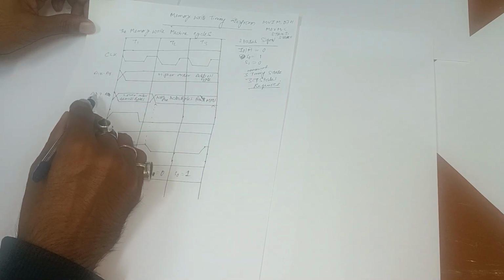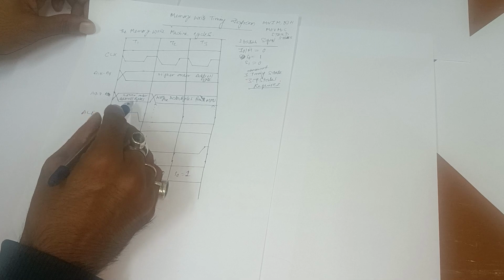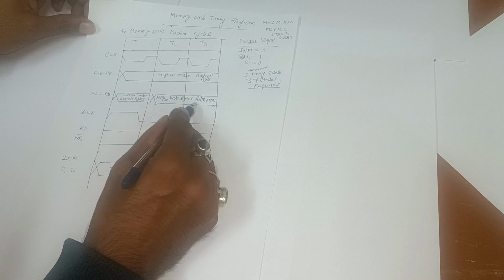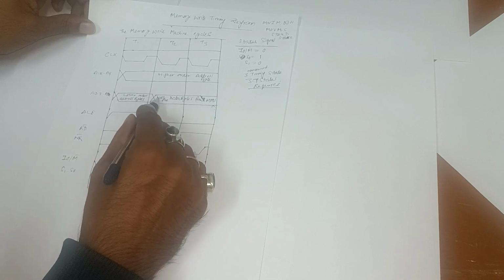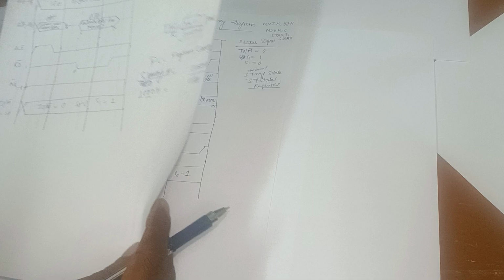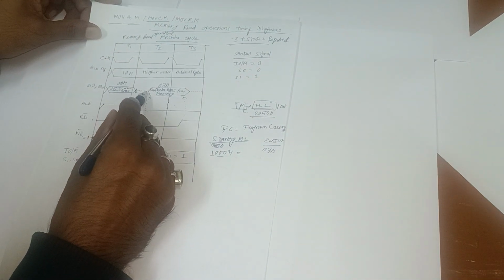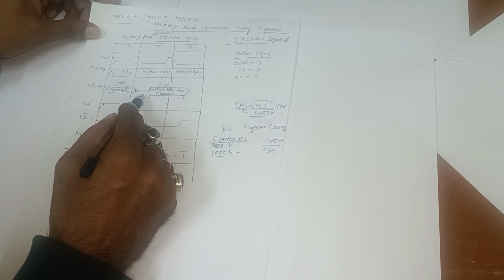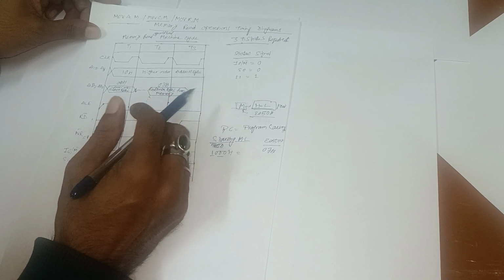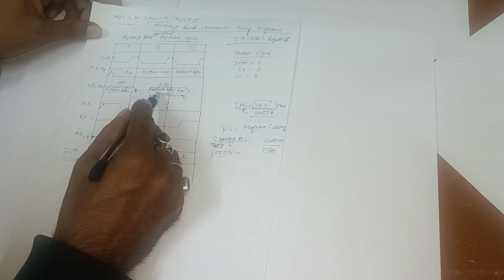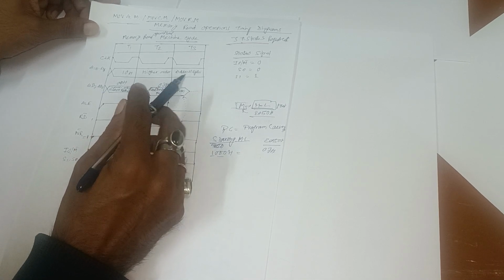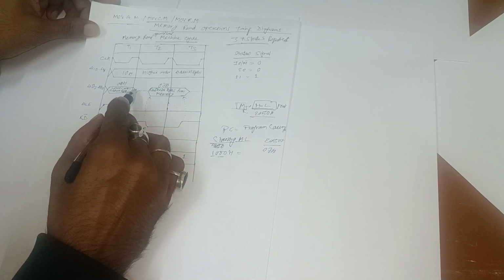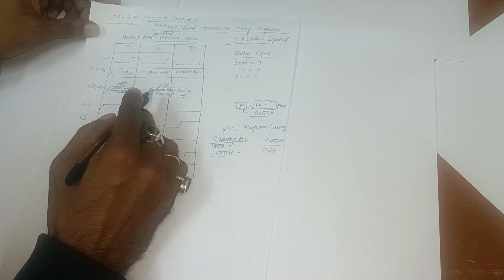Again AD0 to AD7 is the multiplexed bus. For this multiplexed bus, obviously you first have to take the lower order address byte, then T2 to T3. Why is there no gap here? Previously, when I took the memory read operation, we showed a gap. Why? Because whenever you provide the address byte and then read from the memory, mind it very clearly, to read from the memory we need some time. So that is why there is a delay, and the dotted line represents a delay.